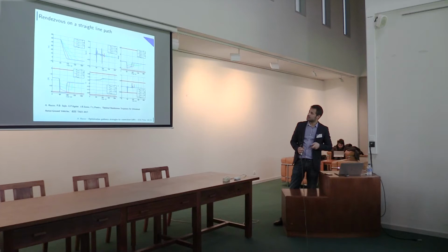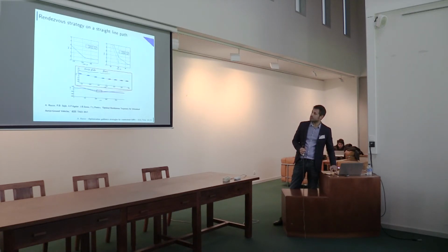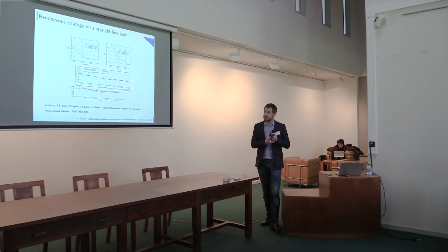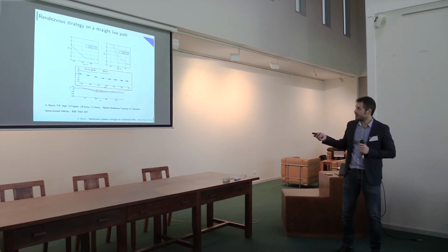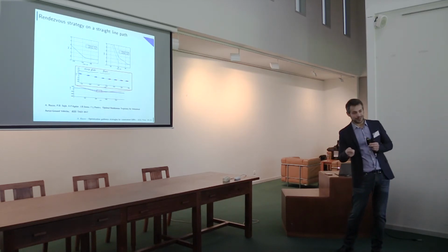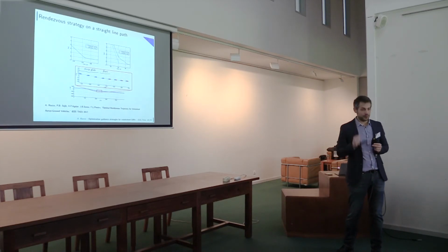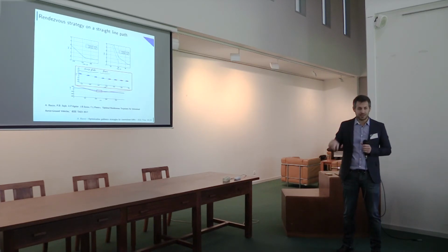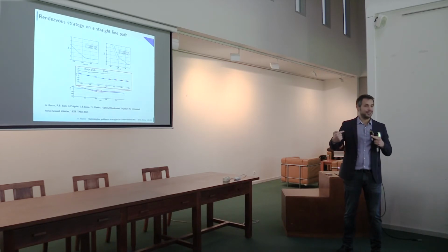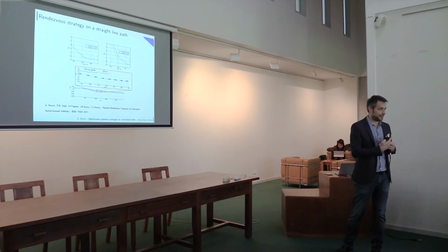which is something smooth, but what I want to show you now is the altitude. The green line is the actual trajectory of our 3D point mass model. And when we have some very aggressive behavior, we are tuning just one parameter, and we are saying, okay, I want to have an aggressive trajectory. We see that the UAV is going very fast, it's decreasing the altitude, and when it is approaching the UGV, it has this behavior. So it increases the elevons, so that it increases as well the angle of attack. The angle of attack is going to decrease the velocity.